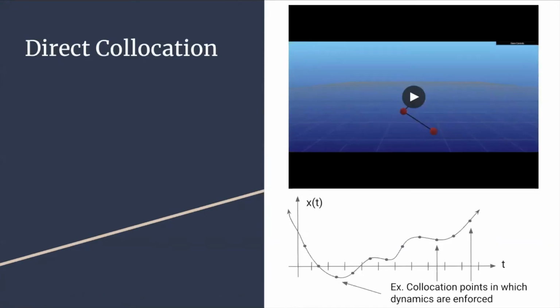Once we had the balancing LQR controller working, the next control task we looked at was getting the Furuta pendulum to balance at the upright, starting from any initial state. Typically, this is done using an energy shaping or swing up controller, in which the energy in the system is pumped up until the pendulum is close enough to the upright position, at which point the balancing LQR controller kicks in.